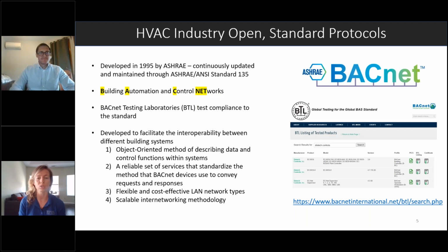You'll notice different controller and device classifications, from BACnet building controller to application-specific controller and so forth. Also, getting more into the fine print and nitty-gritty, you can click on the various PICS statements, P-I-C-S, which show additional documentation of the properties of the device, such as which properties are read-only data versus what you can actually write, meaning what you can command and control.